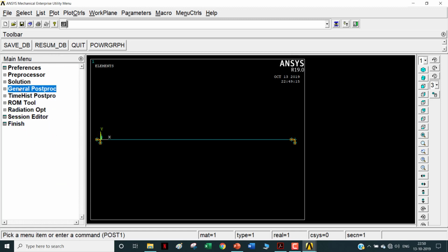So this is all about modal frequency, right? While doing modal frequency analysis, both in theory and in ANSYS, keep in mind that you give all the units as SI units, that is the length unit in meters, the mass unit in kg and the force unit in Newtons. Only that is the issue that you will have, and other than that, you can easily solve this problem and get it for your particular problems, right? So do not give any force. That is also important in modal analysis. Just solve the problem as it is, only by defining the end conditions and also the material properties.